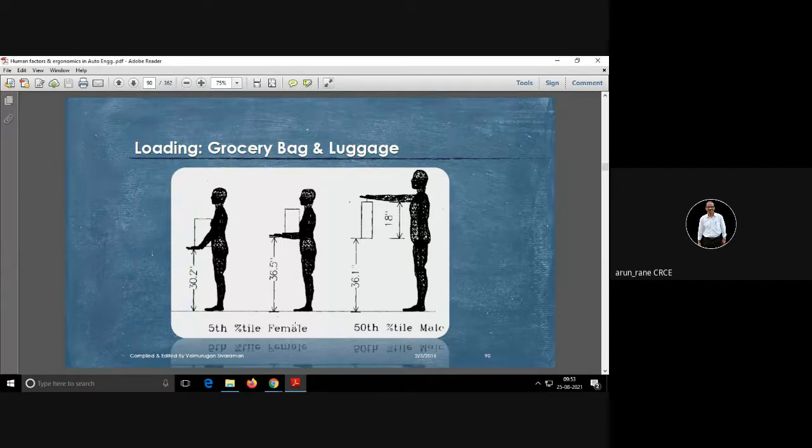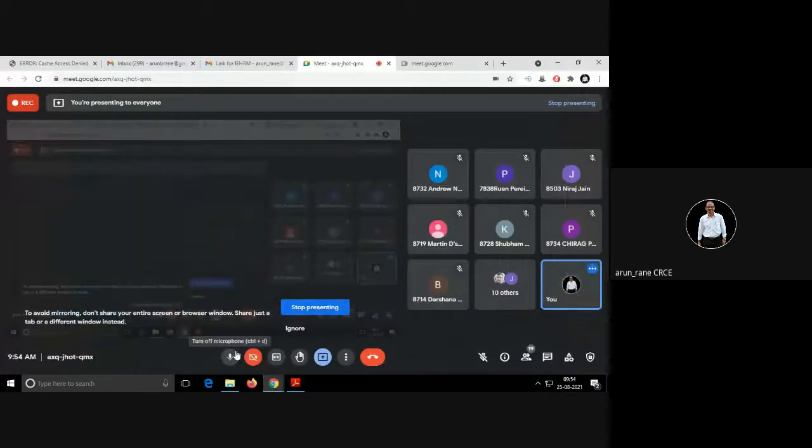Same with your civil work. Suppose you are designing your house interiors, so what should be the position of the wash basin? For this, the data matters. Anthropometric data matters. If the people are tall, as in European countries, the height of the wash basin may be at 4 feet. But for Indians, it will be at a height of 3 feet. Same thing for the location of the electrical switches. These are all based on the data which has been collected.